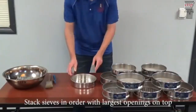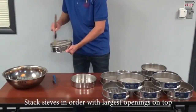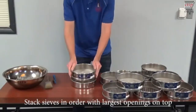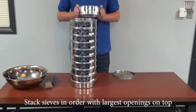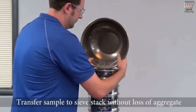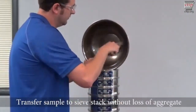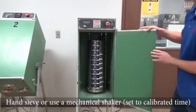Stack the sieves in order, with those having the largest openings on top. Transfer the sample to the sieve stack without loss of aggregate. Hand sieve the sample or use a mechanical shaker set to the calibrated time.